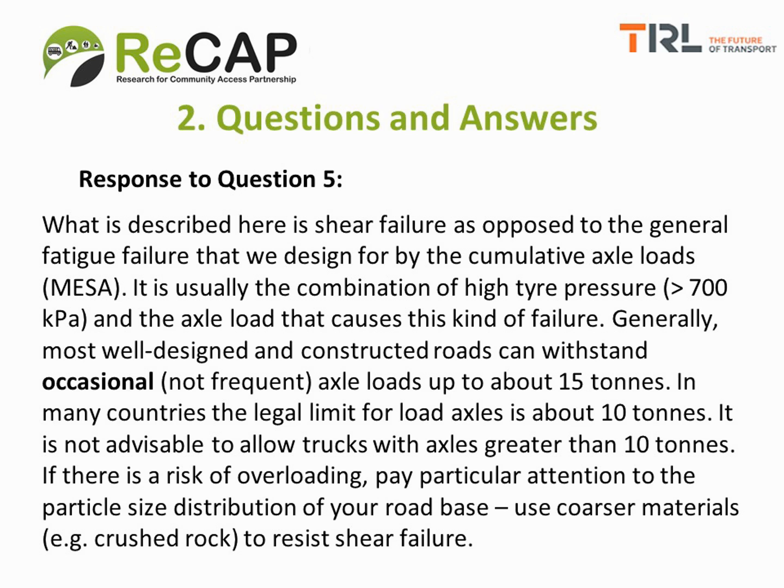But of course, this is a well-known problem. Axle loads are always higher than you have designed for. Operators will overload if they can, and obviously pavement damage is higher than we expect. So this is part of the risks that you have to assess when you're designing the road.